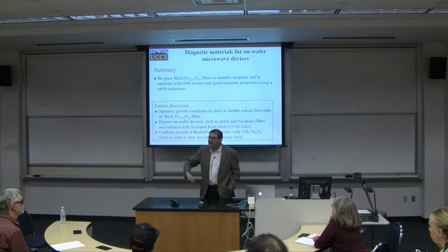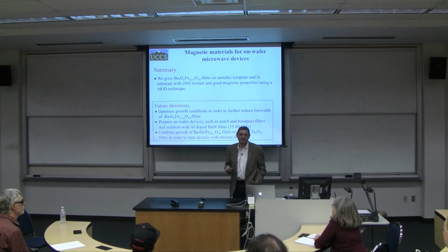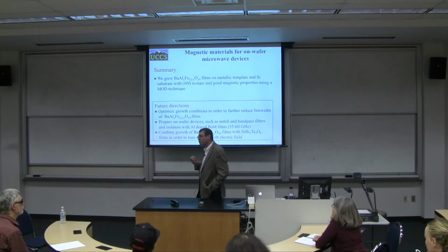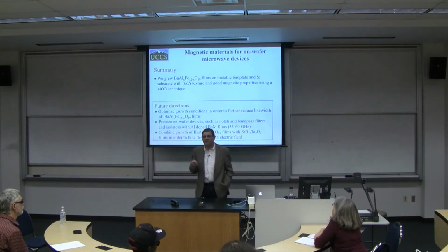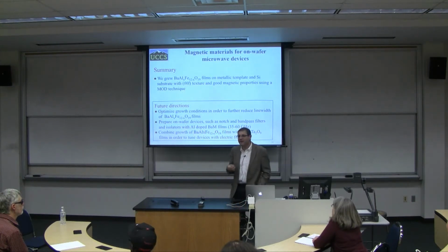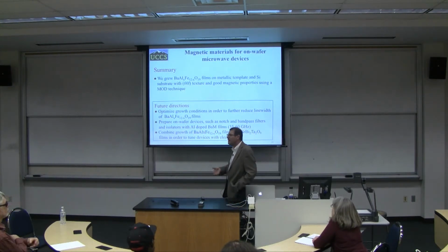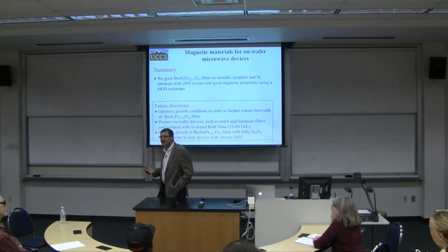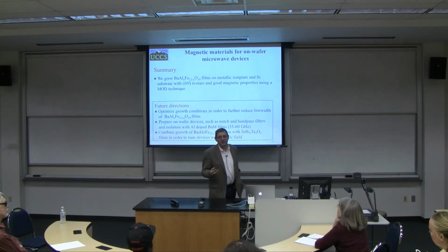There is a big inductor where you have to change the current. This takes time. So if you want to very quickly tune your device, doing this with magnetic field is very ineffective, very expensive from the energetic point of view. You have to change the current. If you can change just voltage, this is a very quick response.